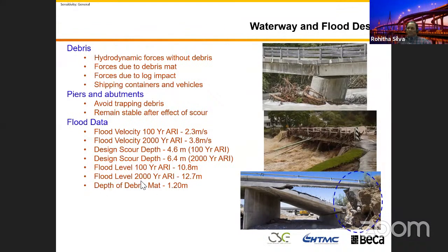And you need to know the flood level in the ultimate limit state, to see whether the bridge is underwater or not. If it is underwater, you need to provide, if required, vertical restraint to prevent the bridge's uplifting. Because if the bridge is uplifted, then the horizontal force due to the water will push it away, and your bridge will displace.